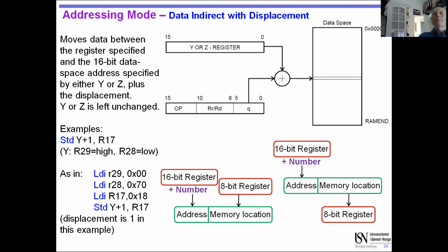So you have to always remember that the general purpose registers are rather limited. We only have 32 of them, right, 8 bits. So we have to put stuff in memory. That's why we're using this. But even more importantly than that, it's not just the amount of register space. It's the fact that if we go direct, we have to know the address when we write the code.